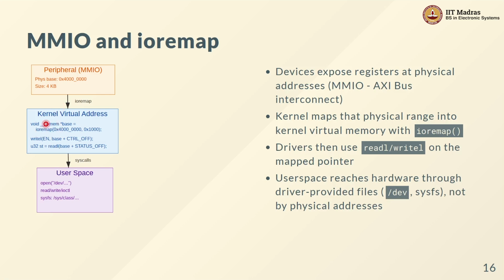Now for IO devices, I do not want that. I want them to get flushed out immediately. So by declaring this attribute as __iomem, it means that anytime I read or write from that pointer, it will directly go and affect the value in the pointer. So you'll see that I also use these functions write-L and read-L rather than trying to just dereference the pointer. This is a cleaner way of